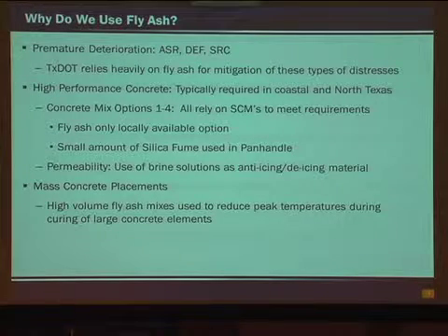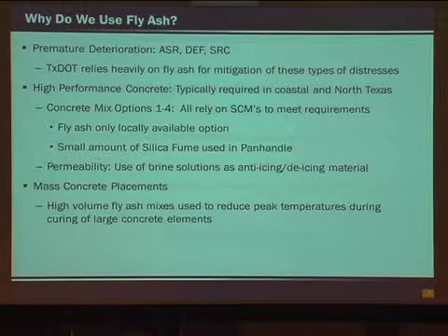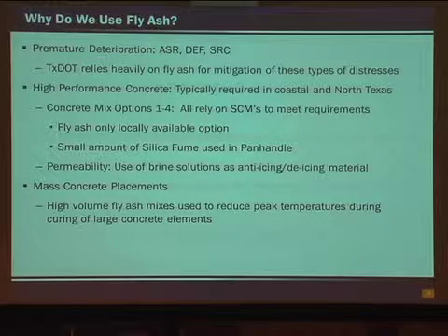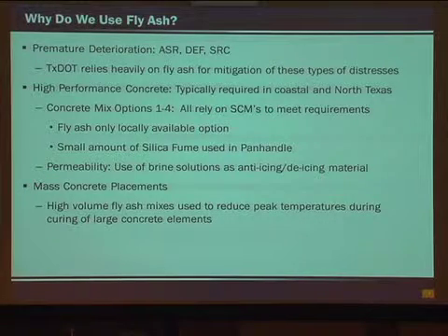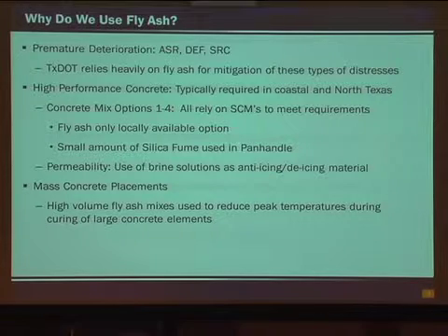Mass placements, we use it a lot in mass placements to reduce the peak temperature. Again, the idea is taking some of that cement out, replacing it with fly ash that doesn't really generate that much heat. And so we can lower that peak temperature and not worry about DEF and things like that.